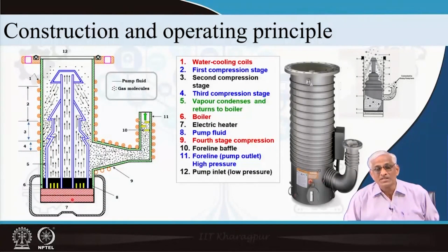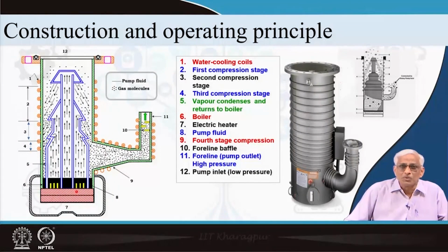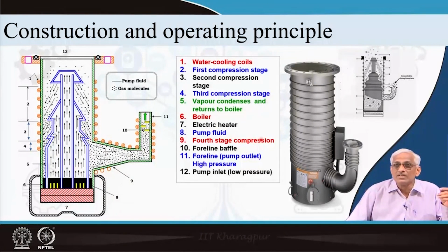It is fully utilized for heating the fluid, and inside the bottom of the cylinder we pour that black looking thing, the diffusion pump fluid, into which we introduce a 3-story or 4-story type of jet assembly. Several people call it by different names, and this type of jet looks like this.